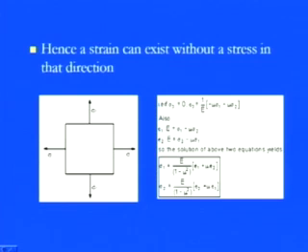So, if you are talking about the first reason, then you see the Poisson ratio will come into the other direction. If you are talking about the first plane, sigma 1, then mu times epsilon 2 will give you the deformation measure, and if you are talking about the other plane, sigma 2, then mu times sigma 1 will give you the measure of deformation. So it is pretty simple: if we are talking about principal stresses or principal strains, we have to be very careful about what kind of loading is there, and what the interactive effect is on the other two directions. So, this was the principal strains.